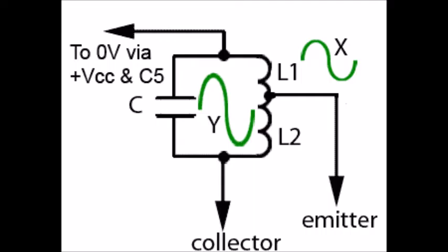So we are trying to set up a resonant LC circuit which only picks up the frequencies that are nearby 1 by root LC, that is, we are changing the C to get this frequency near to 93.5 megahertz, and these nearby frequencies we pick up and they are processed in the later stages to get the final purified signal in a better way.